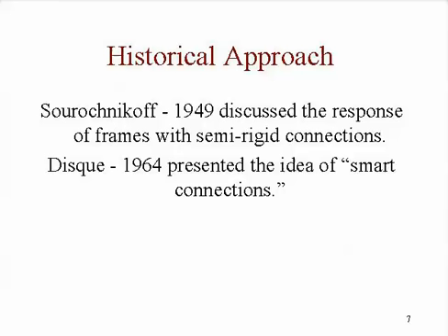Now, these were the connections designed under the system called Type 2 with wind. They were connections that knew when they were carrying gravity load, they were not to carry any moment, but when the wind blew, they were to carry moment.